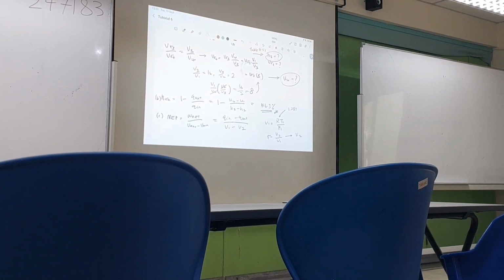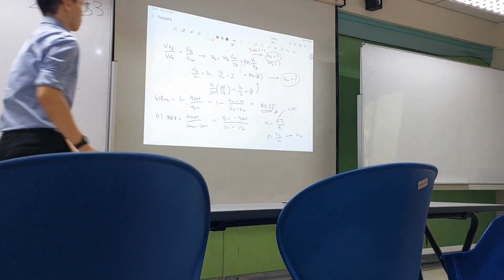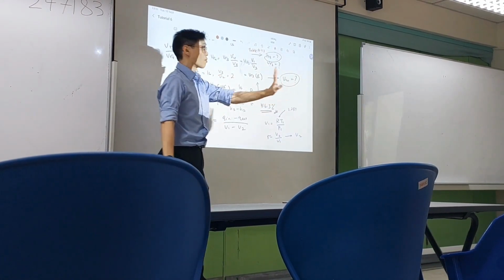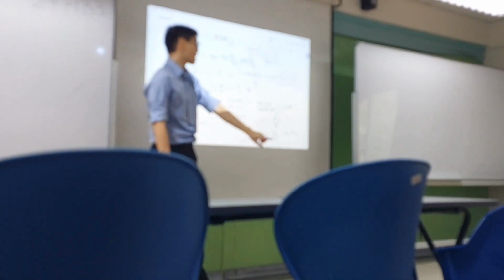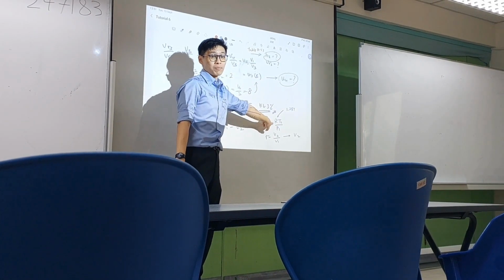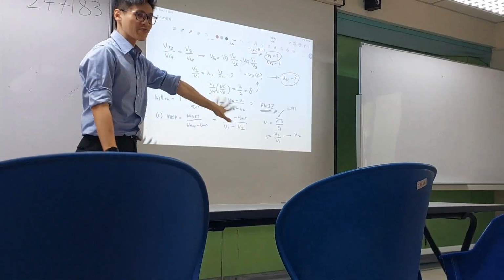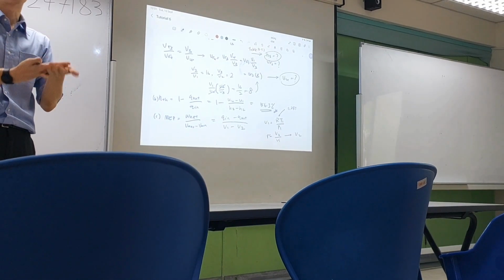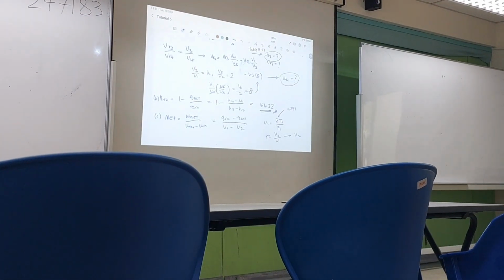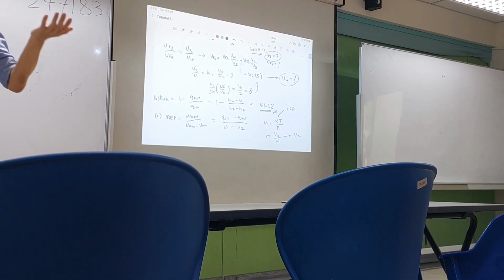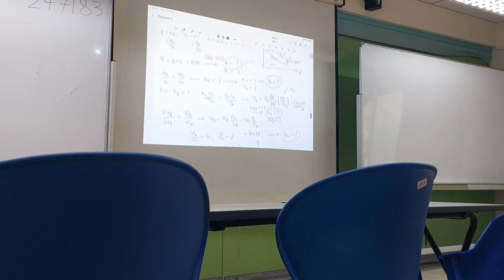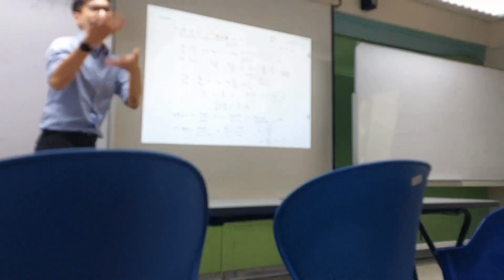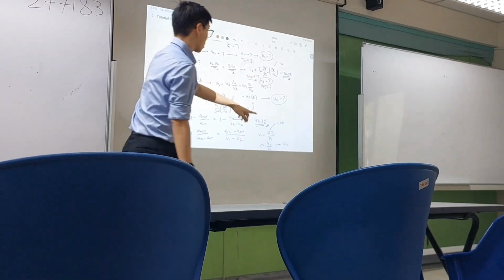So now in general, we try to minimize the usage of this equation because we are using a variable specific heat method, meaning this R value actually will change also because the C is changing. But usually intake is fine because intake is approximately atmospheric pressure. Like you see here, we are using 95 kilopascal, temperature is 27, which is the normal temperature that we use. That's why you can use 27.